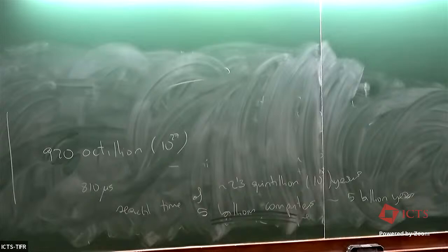If there is precession, then there is going to be the rotational frequency plus or minus the precession frequency. But there could also be some kind of unknowns, and I could consider other things, in which case I leave some freedom, or because I don't trust completely the ephemeris. I mean, all these ephemeris data will have some errors.